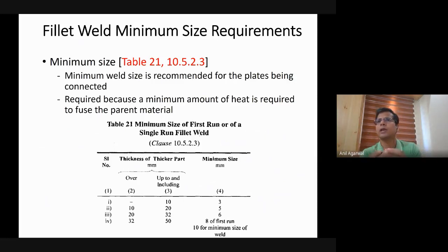Now we know how to calculate the strength. Then there are some considerations that you have to pay attention to when you design the fillet. One thing is the minimum size of the fillet weld. For a groove weld, you don't have to worry about the minimum size, because a full penetration groove weld has the same size as the plates it is connecting. But for fillet welds, the size of the weld can be anything.